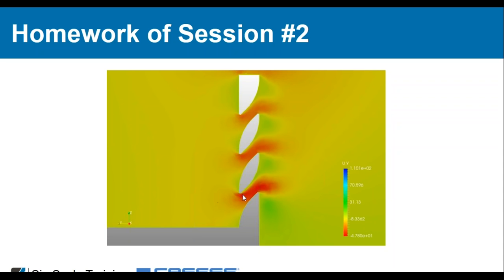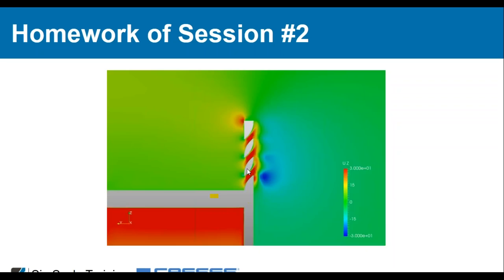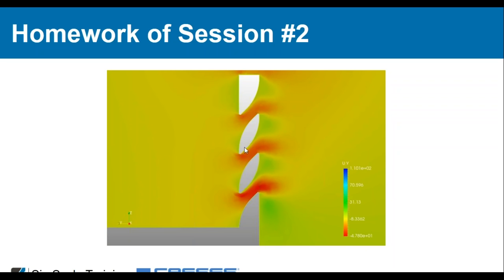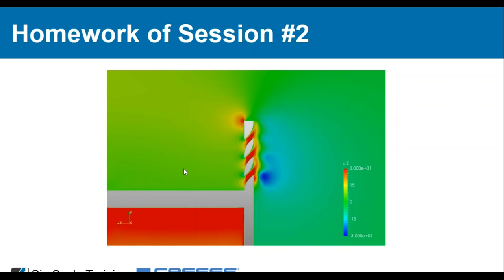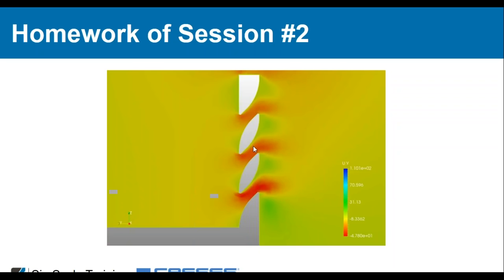Here you can see that in this direction the flow is leaving this part, in the inner part behind the end plates, with around 40 meters per second in this direction. This is for sure just the Y direction, so the magnitude will look different, but this is the role of these louvres: they allow air with higher pressure, which we'll see later on, to leave. This will reduce the overall pressure at the upper side of the wing, reduce the drag and increase efficiency.